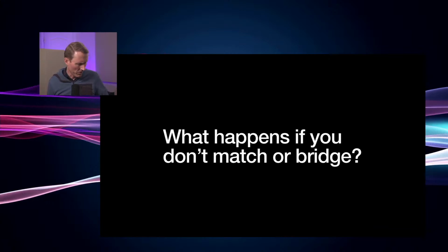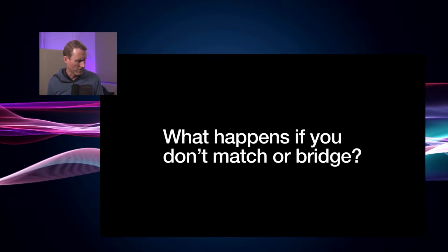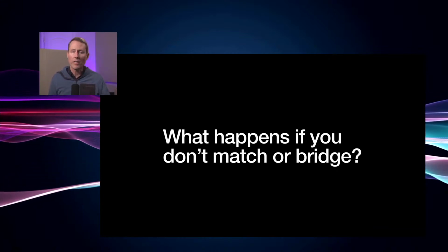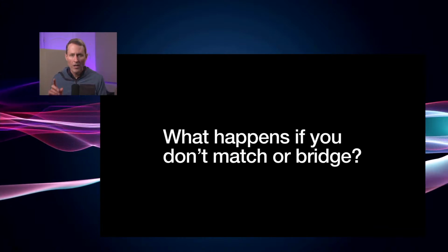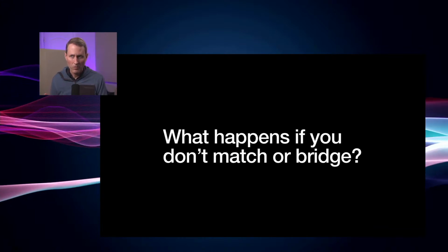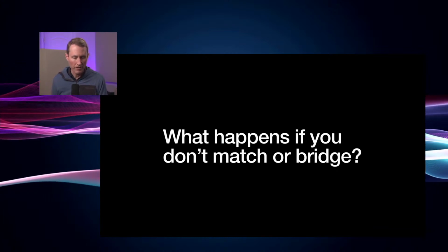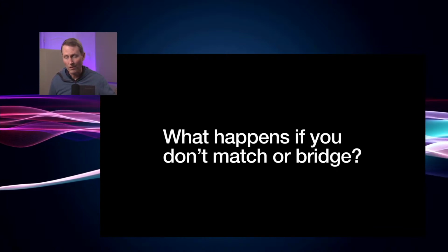Let me just bypass the compressor altogether, so it's not going to be doing any compression. The interesting thing about the 6176 is you can change the input impedance, and it has two settings for microphones. 2000 ohms, which is pretty typical for modern preamplifier designs, and then you can also switch it down to 500 ohms as well.